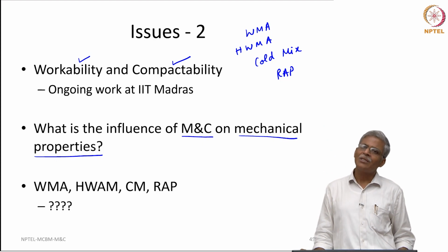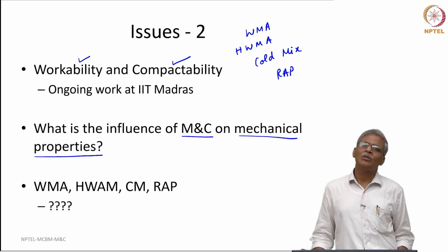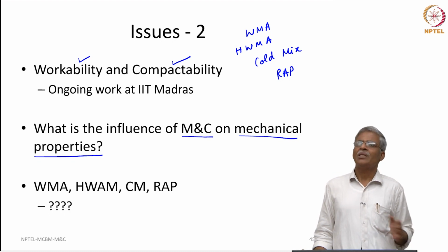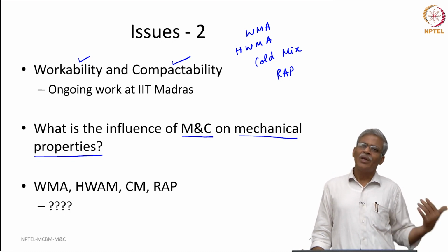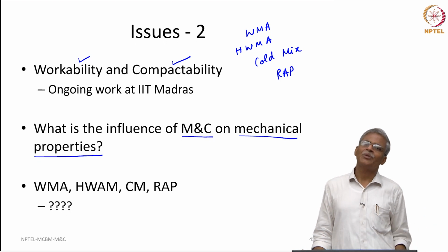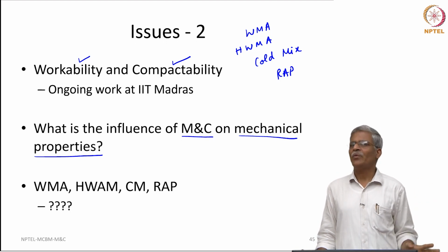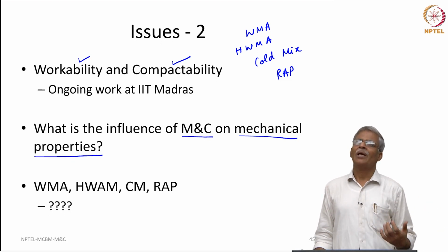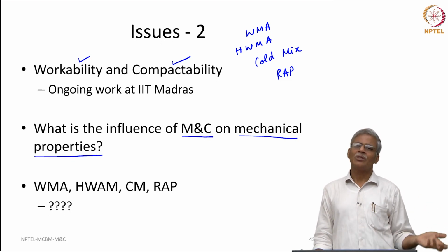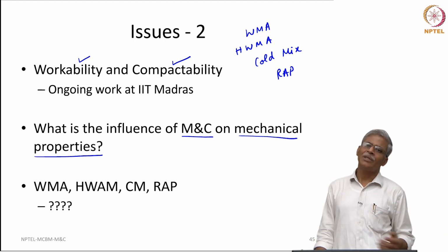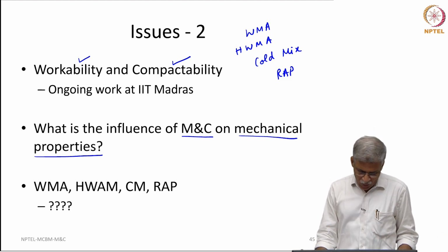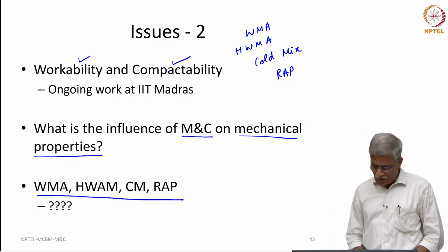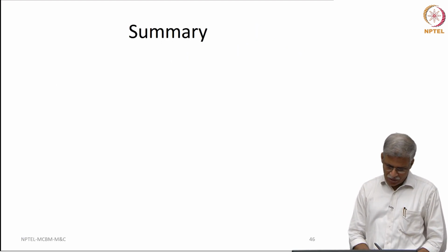In many cases it was found that because of poor construction practices related to mixing and compaction temperatures, very good modified binders which have proven to work very well have not been able to showcase their improved mechanical performance, just because the compaction has not really been done very carefully. And so, when we have these kinds of mixes, it is always necessary to find out these things, right.